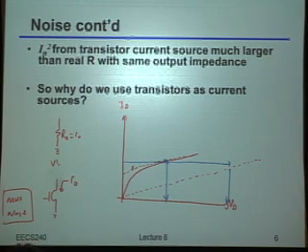So in fact, it may indeed be the case that even though pushing the minimum voltage down like this caused you to have extra noise from the current source, if it brought you back more in terms of the swing you can get, from a net SNR standpoint, that might actually be a much better thing to do. Does this make sense to everybody?